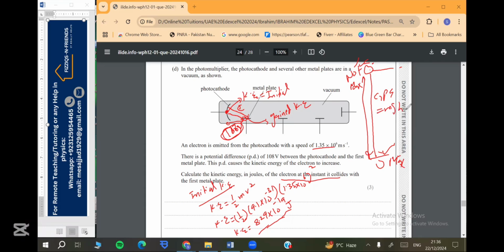Now it is electronics. Okay, so we see that this point is having, for example, 100 volts, and this point is having 208 volts. So there is a potential difference of 108 volts. 208 minus 100 equals 108 volts. So when an electron moves between these 2 points of different potential, it will gain some energy, just like a falling ball is gaining some energy, right? So again, we say change in Ke equals change in Pe, right? In electronics, the concept is absolutely same, but here we have electric energy, not gravitational potential energy.